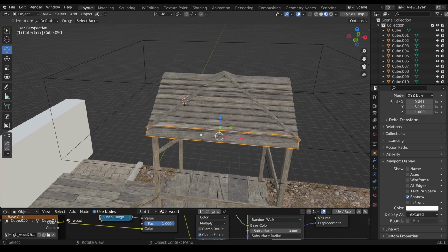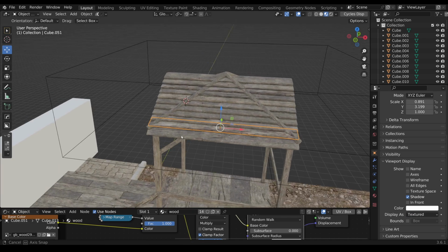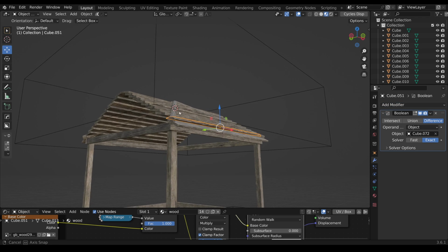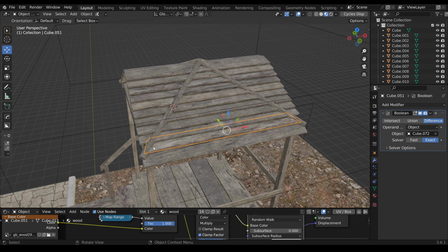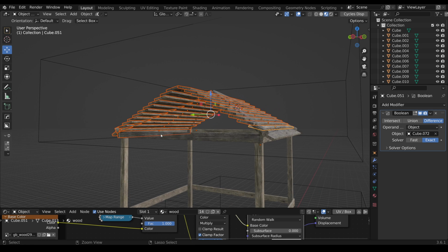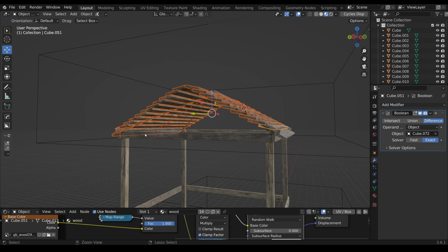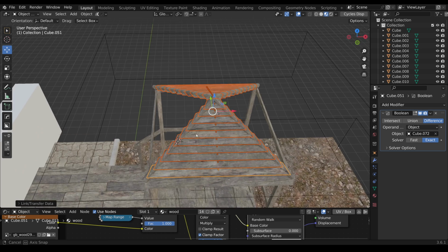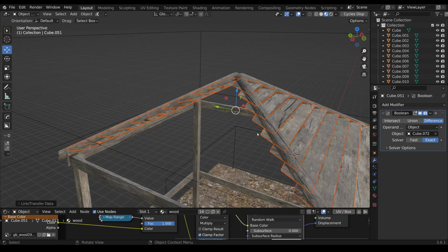Select a plank, preferably one we want to cut, add a Boolean, and choose our Boolean object as the target. I see it's not quite right yet, but we'll fix that after we've cut the remaining planks. Select everything we need and deselect what we don't. From the coloring, we see that our plank is the active object. So, Ctrl-L, copy modifiers, and we're done.